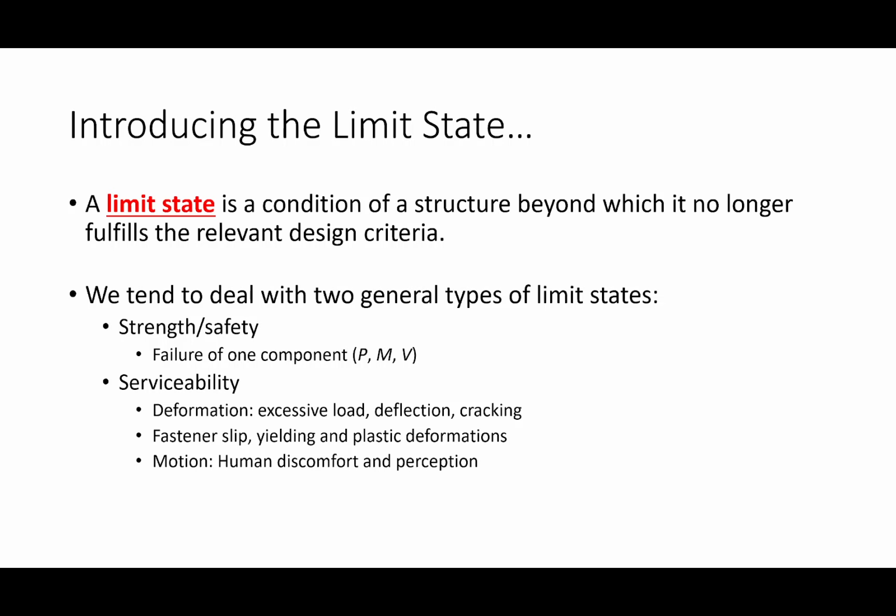Now, if you're in a building and you see some cracking on the plaster of the roof, it does not mean the roof is going to fall down and kill people, okay? But it does mean that the roof is not performing its intended function. I don't want a roof where I put some people on the floor above and the ceiling plaster cracks. I don't want that to happen. So I need to provide beams that are stiff enough such that that doesn't happen.